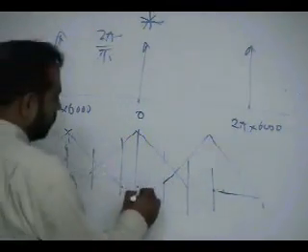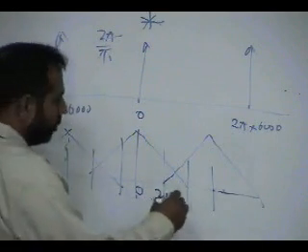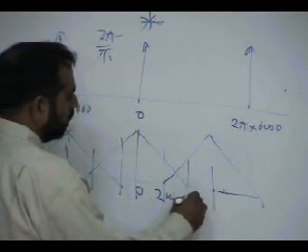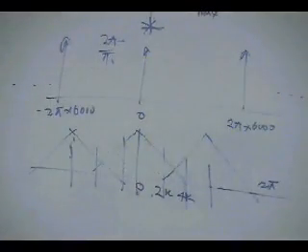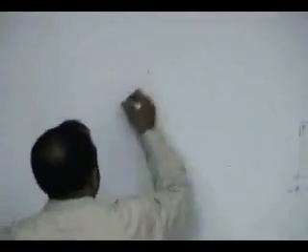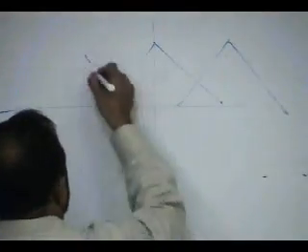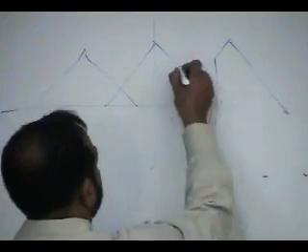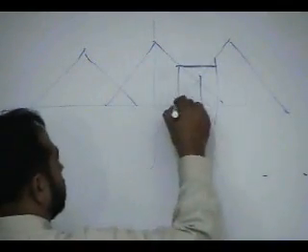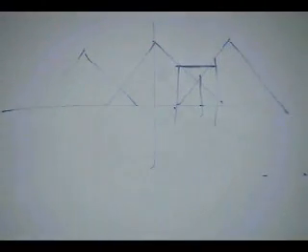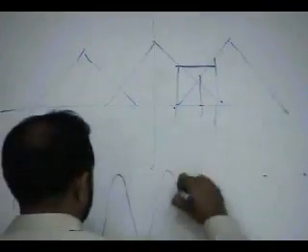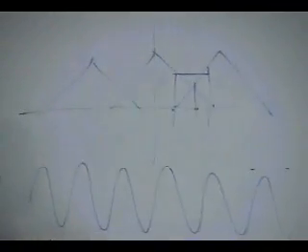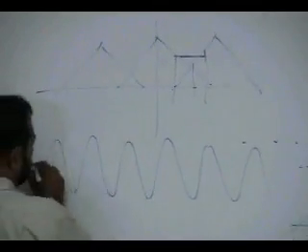You will only get the signal from 0 to 2k correct. 2k going to 4k will be corrupted. Right? The axis is 2 pi into 2k, 2 pi into 4k. It will be corrupted. Why? Because this is what you get. If you don't sample fast enough, you are going to corrupt the 2k to 4k signal. And last time I showed you that if you don't sample fast enough and you are sampling slower,